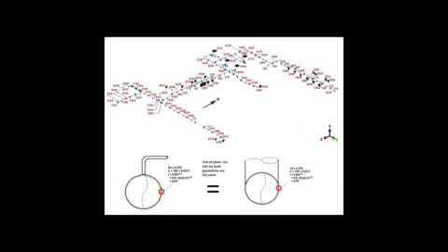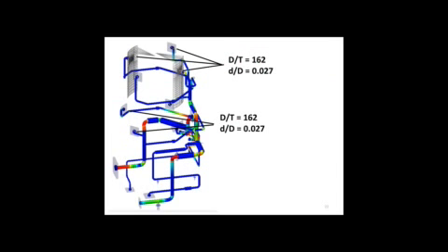Let's take another look at a typical piping system. Okay, big piping system, the first thing that comes to my mind is the high SIF problem. If you run this model in Caesar without making any modifications, you have no stress problems, everything is fine, and stresses are all very, very low. If you look at the criticality count, if the stresses are less than 20%, you can divide by numbers. So if you've got a very low criticality count, you'd never worry about it. As soon as you start having higher stresses, or tight portions of the piping system, or small D over T ratios where the SIFs are way off, now you want to start zooming in and taking a look at it locally.